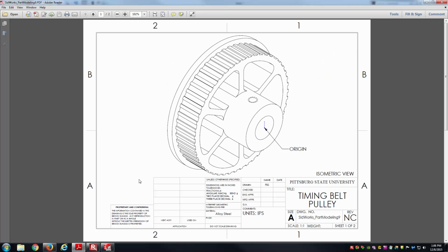So a little bit of thought process. How are we going to map this thing out? First, I'm going to start off using the Revolve tool in order to create the majority of the geometry. I'll create all the solid geometry except for the teeth that are wrapping around, that pattern of 50 instances. Then we can start removing material as needed. We can put that 3/8-16 hole in, create the cuts to create the spokes, and then also create the add-on material for the teeth itself. It's a very quick run through of how I'll go about modeling this part.